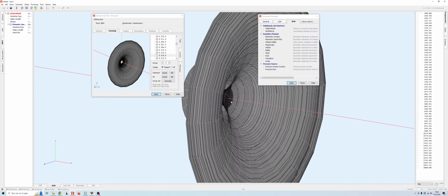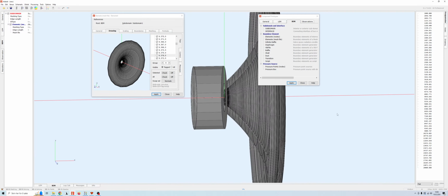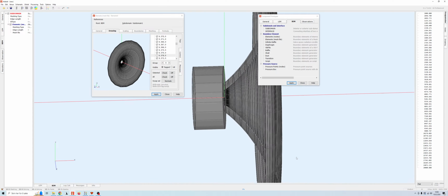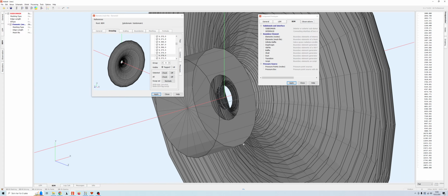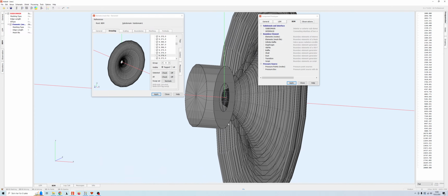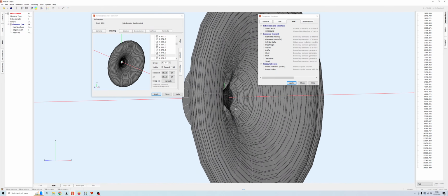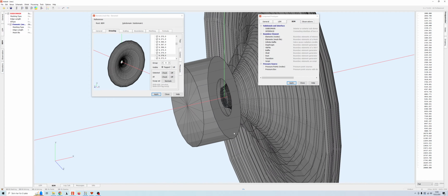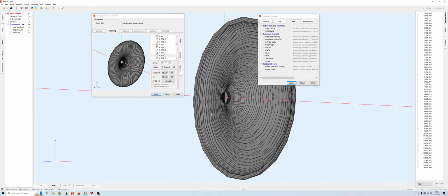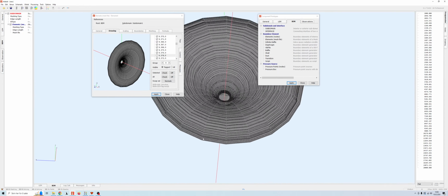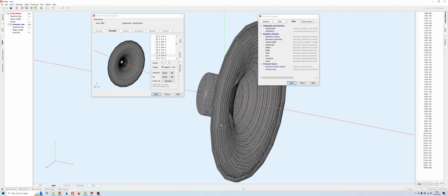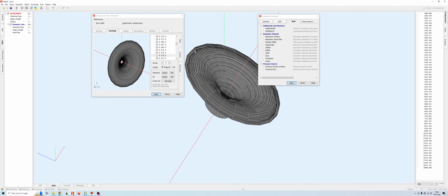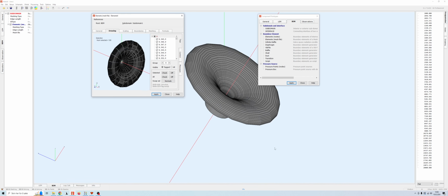Now for some reason, in circular symmetric mode, it really likes just changing the direction of the normals. So now we can see inside the chamber. And if you can see through a structure, that means you're looking in the same direction as the normal is pointing, which means that the normals are pointing inwards here, which they're not supposed to. The boundaries is where the normal is supposed to point to, and in this case, the boundary is outwards. So we simply click on this, normal selection swap, click apply, and now it looks fine.